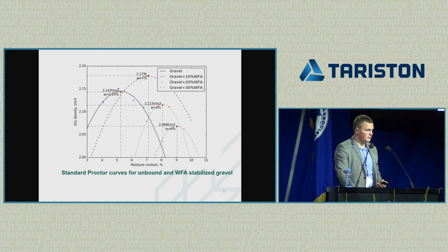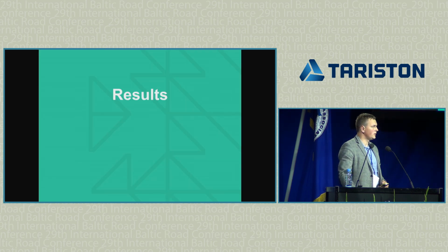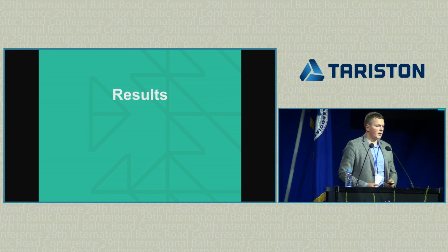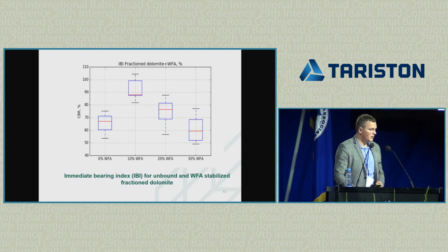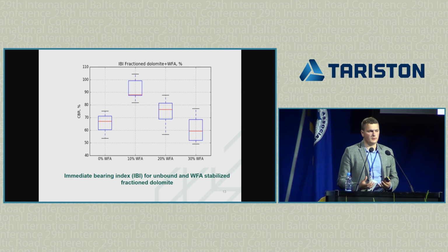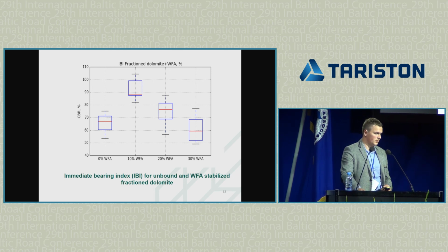So we picked those optimal contents, and we tested, as I said, for the immediate mechanical performance in the CBR test. Immediate means just after the mixing, so to get some properties to see how this material works just after the mixing with binder. So this is what we got.